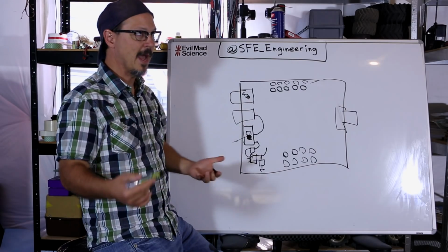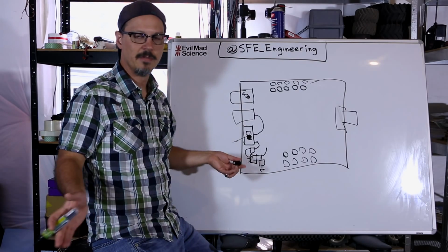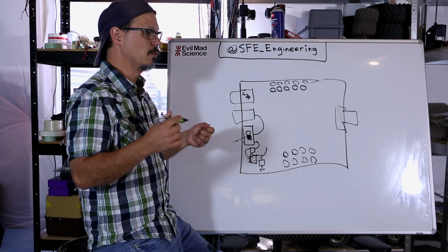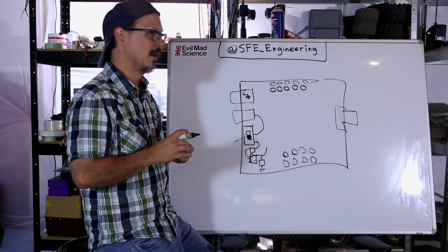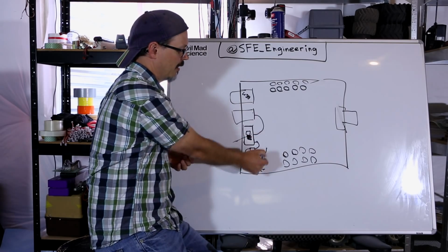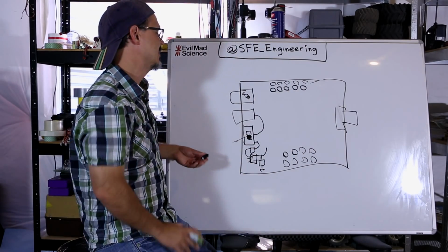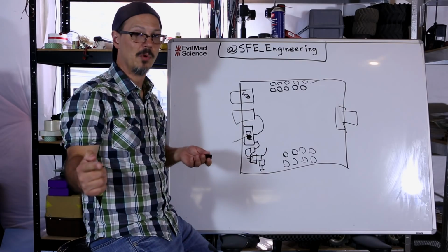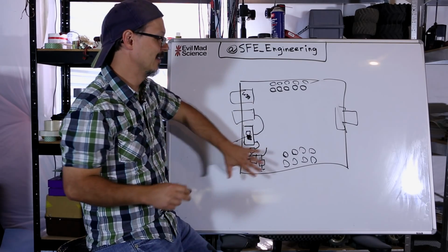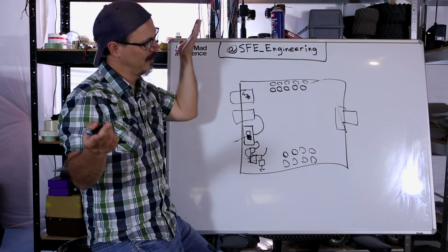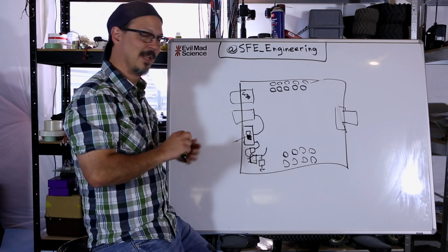Now, in the schematic, there's potentially a zillion different places that VCC is going to need to go. But you cannot realistically run a line from here to every last component that's got to be covered by VCC. Now, if you're running a 4-layer board, much easier, because you've got a layer of copper underneath that you can just punch down to. That's my VCC. It's easy. I can get it anywhere. With a 2-layer board, you have to plan a little bit.